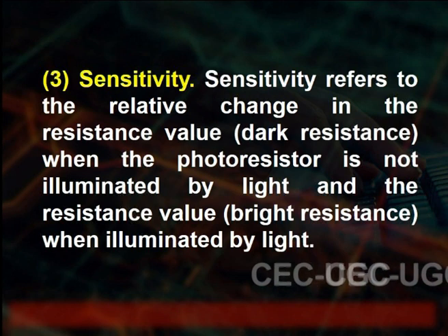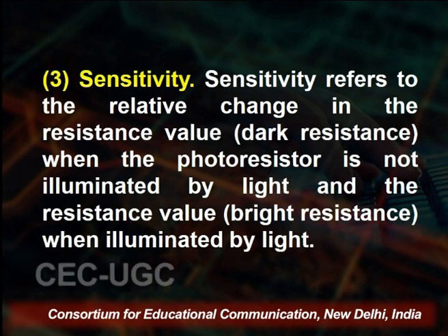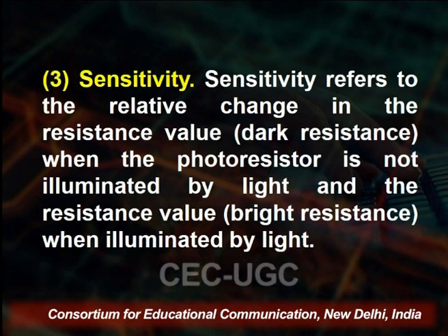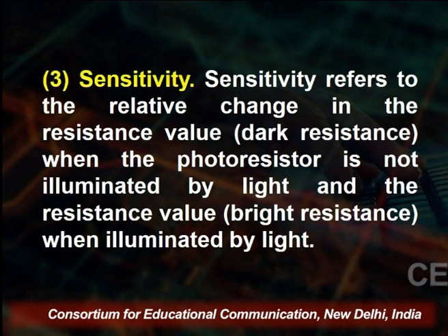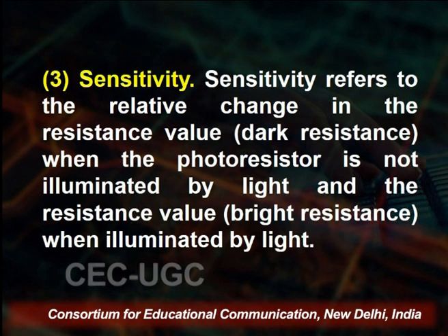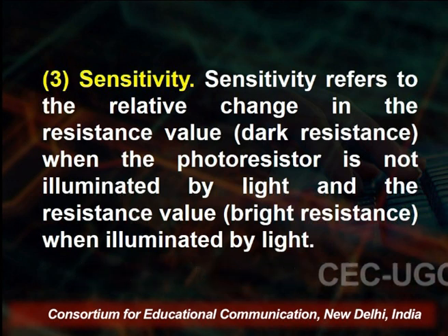Now, the third parameter is the sensitivity. Sensitivity refers to the relative change between the resistance value, the dark resistance, when the photoresistor is not illuminated by light, and the resistance value, the bright resistance, when illuminated with light.